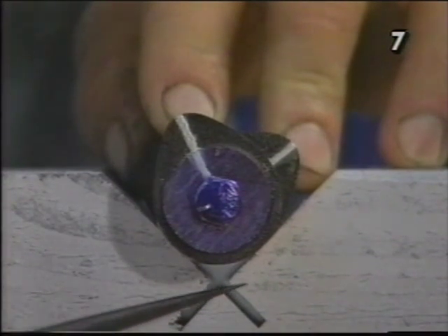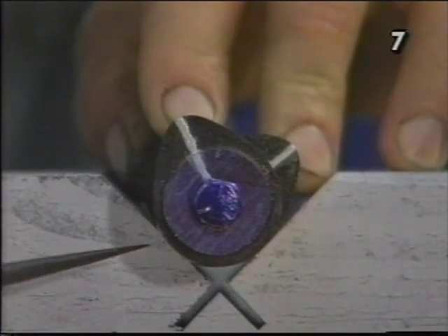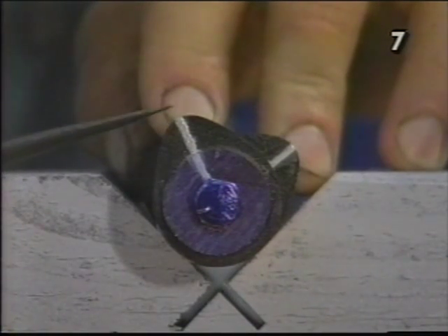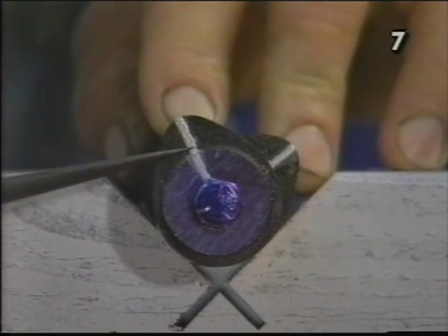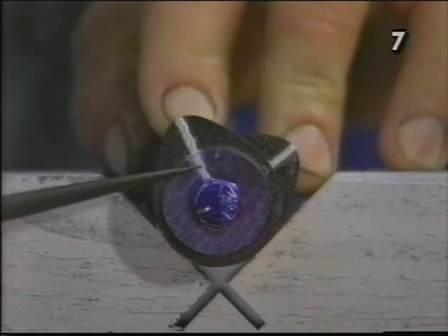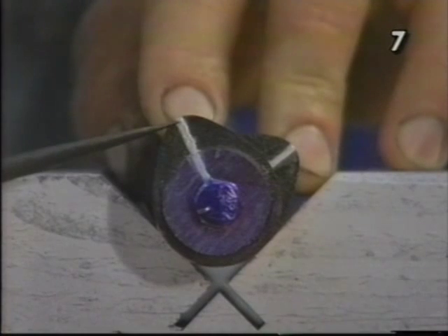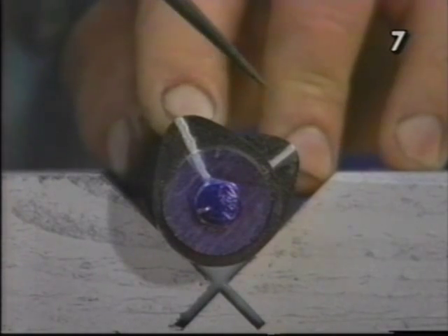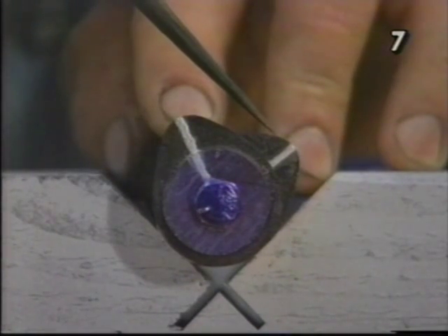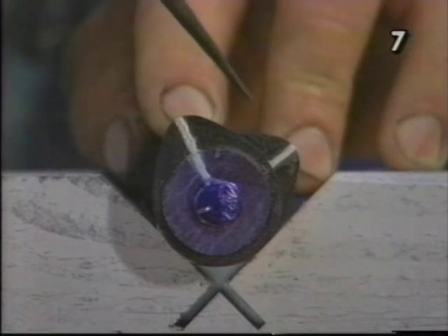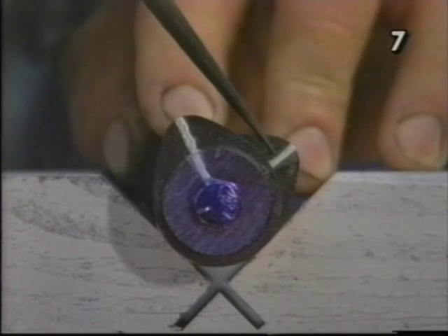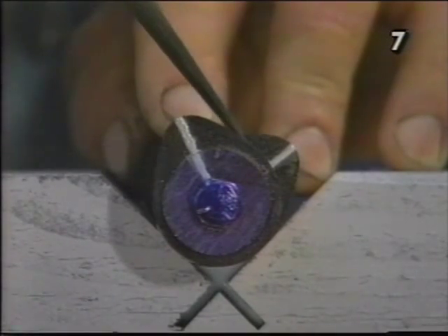You have your heel at the bottom, clearance ramp, flank, nose, and this line represents the center line of this particular lobe. We're going to assume that this is the intake lobe for the rest of our discussion. Behind it is the exhaust lobe for the same cylinder. It also has the painted on center line for designation.